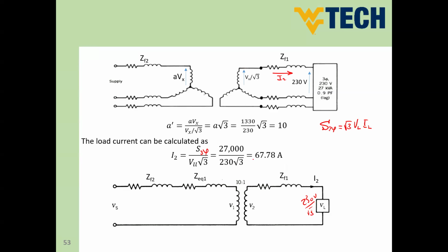So what we can do now is start solving the single line diagram, because now we converted the delta to Y. Simply we can have the calculated current here, which is going to flow in our transformer and will be transferred to the primary side using our turns ratio of the three-phase. And then we have the feeder impedance here. We have everything in the primary side, so we can do our calculations based on that.